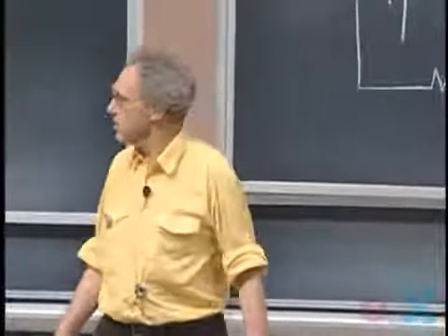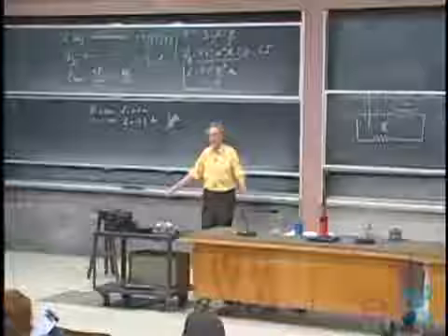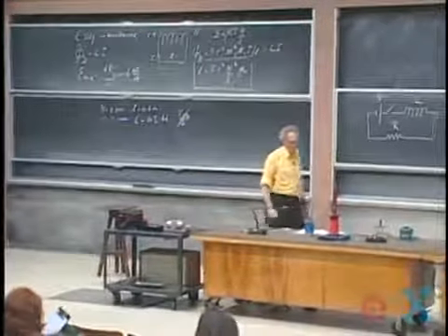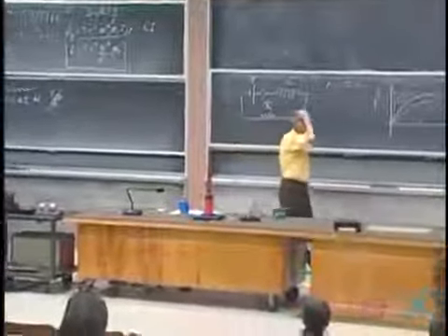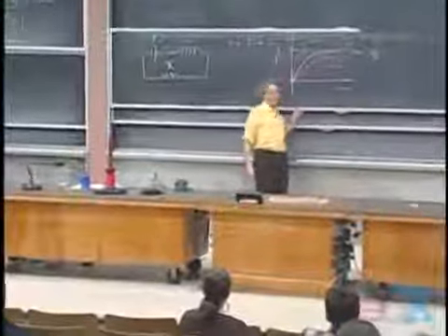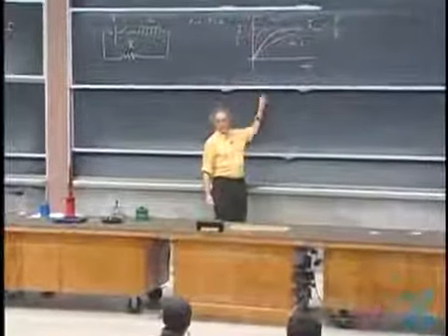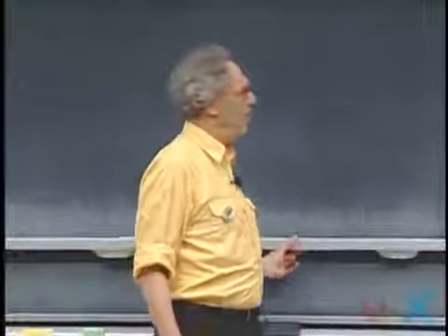They advise you to use Kirchhoff's loop rule, which says that the closed loop integral around the circuit is 0. That, of course, is utter nonsense. How can it be 0? Because there is a change in magnetic flux, and so it can only be minus dΦ/dt. I advise you to go to the 8.02 website and download a lecture supplement in which I address this issue and hit it very hard.